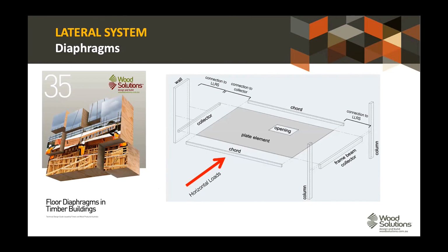WOODSOLUTIONS has a really good design guide for floor diaphragms in timber buildings, which I recommend you reference or have a look at. It takes you through the models for the detailed design. So the Eurocode guide giving assumptions for stiff diaphragms is really good, but it's also really useful to build that confidence yourselves by running through some designs for some diaphragms and testing some stiffnesses computationally.